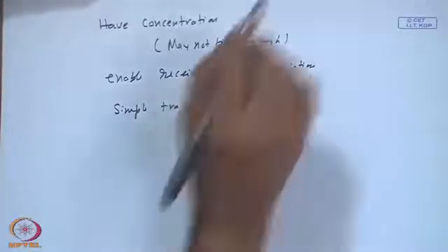You may recall that we discussed 5 cases of tracking, simplest being east-west axis with one single adjustment per day, such that phi minus beta is equal to delta. The next one, that phi minus beta you keep on changing depending upon the time of the day, still the axis being east-west. Of course, the other 3 deal with the north-south axis and a perfect tracker of 2 axes. So, if you have a simple tracking and the concentration ratio is not very high, we may get away combining the advantages of a flat plate collector, mainly of accepting diffuse radiation and minimal tracking, yet providing a higher temperature working fluid that is being delivered by the concentrating collector.